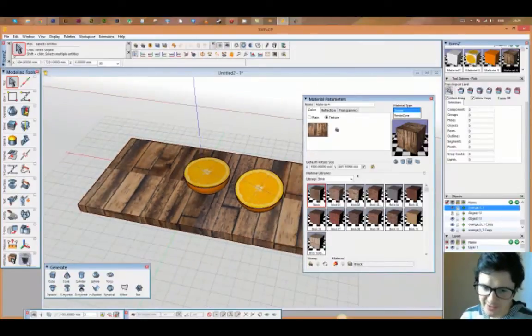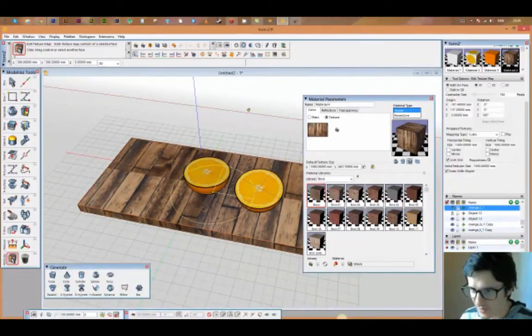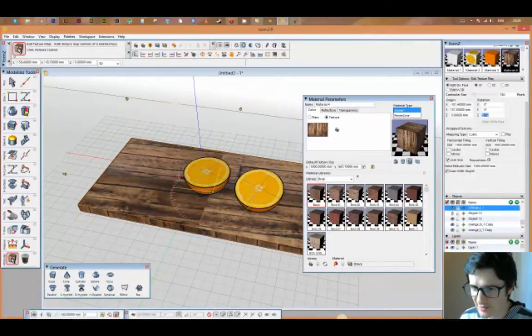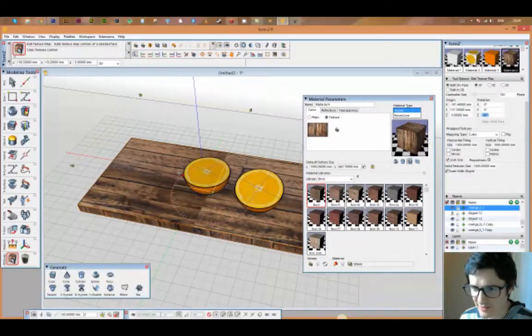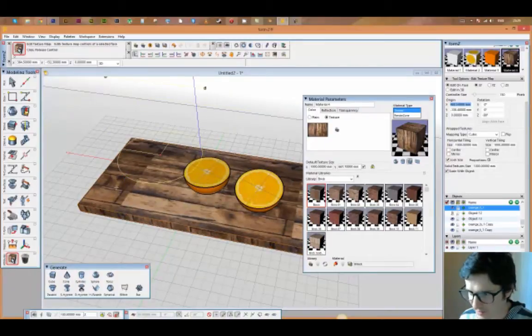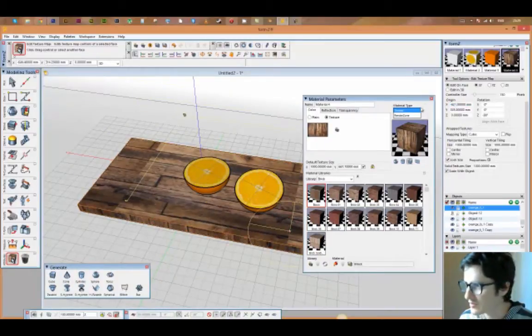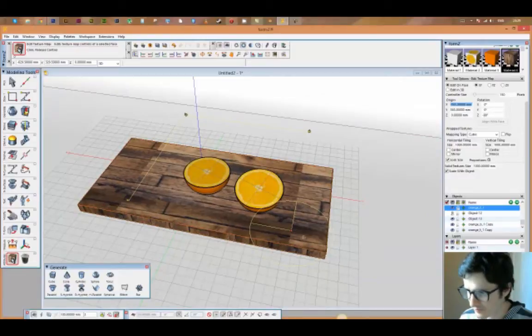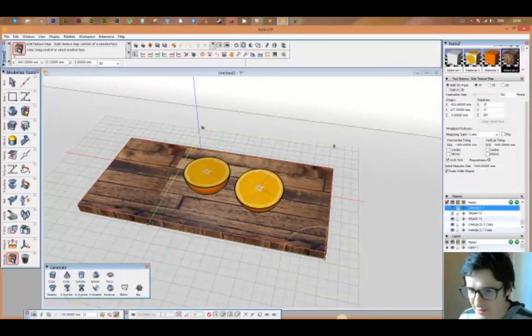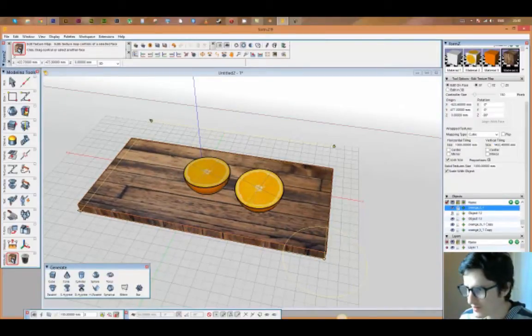Now, again, we've got to use our Edit Texture tool. And this time, we'll just click on this outer ring and rotate it until it's in the correct orientation for us. Then I might move this, let's see, move it down to this corner, move this box. And what I'm going to do is adjust this point out to here, and that point looks okay. So let's give that a render.